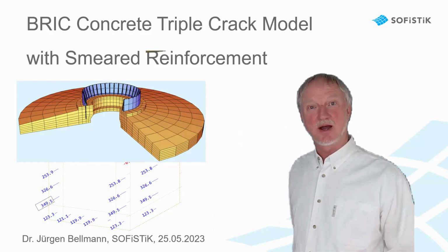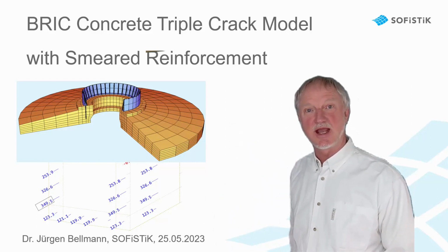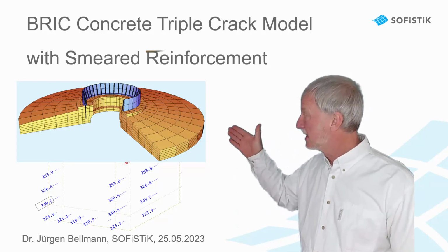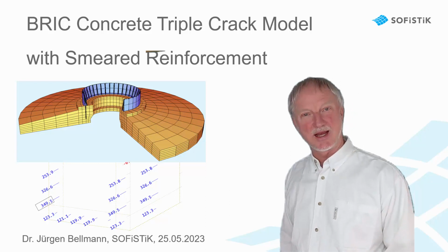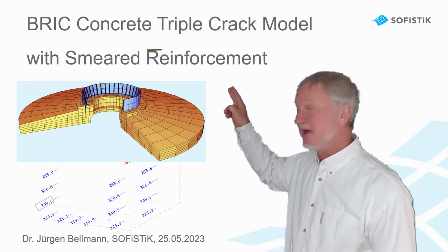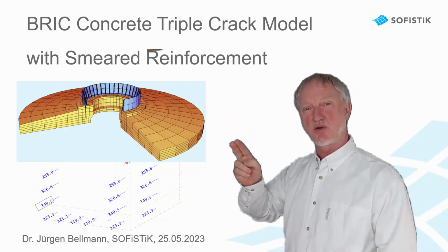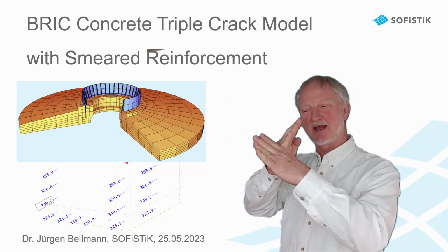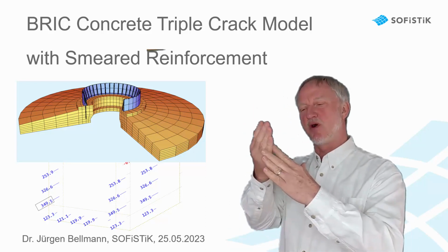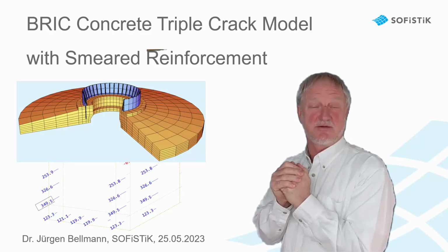Hello, I'm Jürgen Bellmann from SOFiSTiK, and today I want to show you our nonlinear concrete model for brick elements. We call it triple crack model because 3 cracks can occur in every element. The cracks are perpendicular to each other.